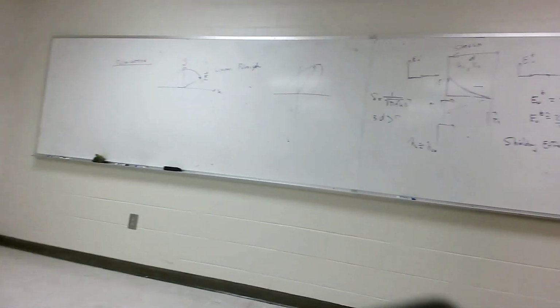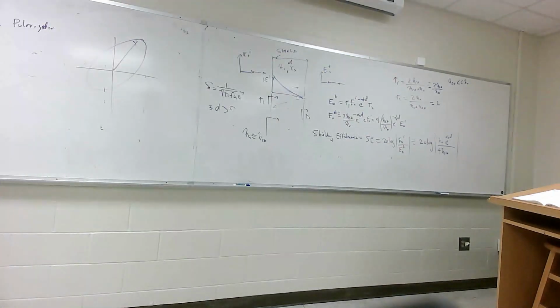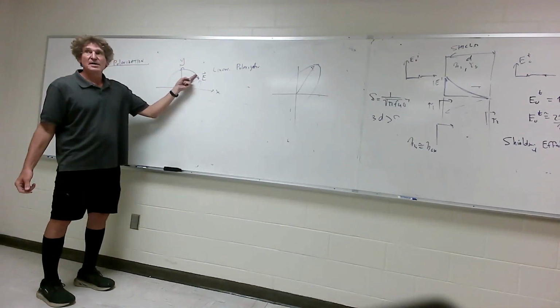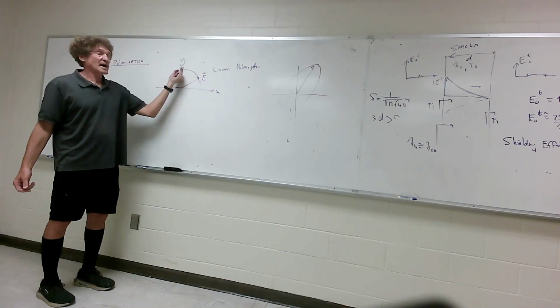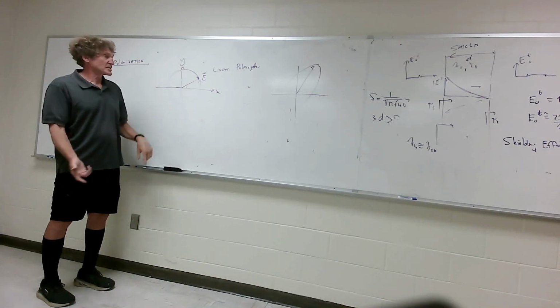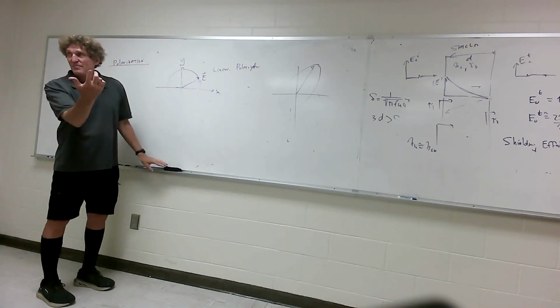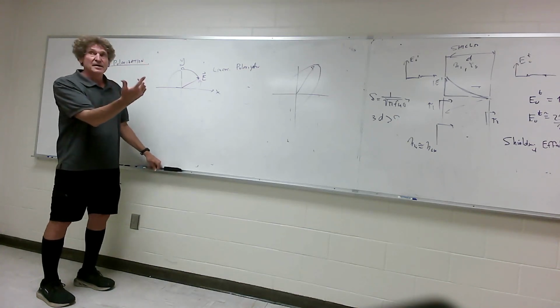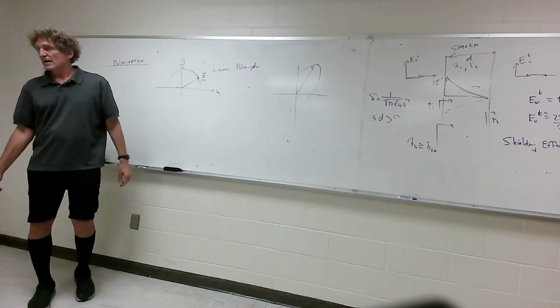For polarization problems, the easiest thing is you're going to be given time domain waveforms plotted at 3 different points in time. You can just trace: if omega t equals 0, it's here. Omega t equals 45 degrees, it's here. Omega t equals 90 degrees, at z equals 0, you know it's going what? Circular. Clockwise or counterclockwise? Right hand, from the direction of propagation. This would be right-hand circular polarization, right?